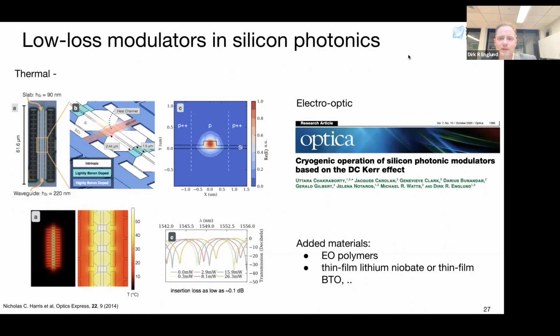If you look at the polarizability of silicon, and look at the third order term, chi3 multiplying the electric field, and you plug in a DC offset E_DC that's applied by reverse biasing, for example, across a junction across the silicon waveguide, plus an electric field that is AC or perhaps even optical.